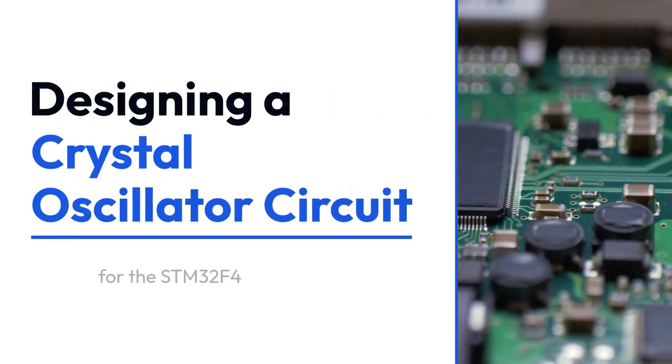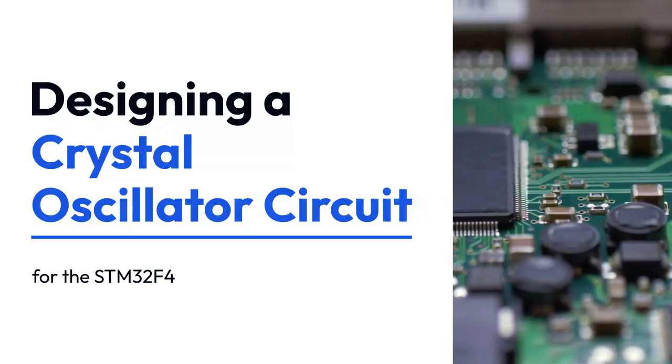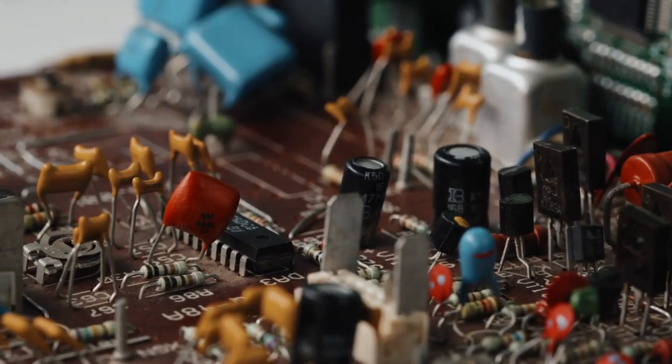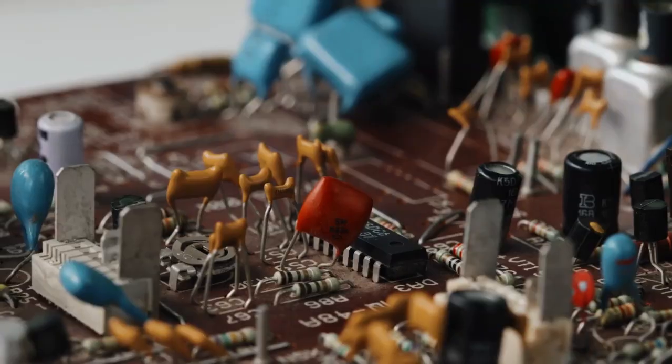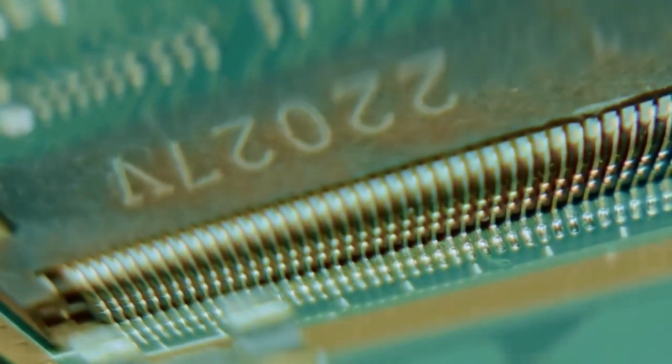We are diving into a crucial topic for any STM32F4 project, designing a crystal oscillator circuit. This circuit is the heart of your microcontroller's timing. It provides the precise clock signal that the STM32F4 needs to run accurately and reliably. Without a stable oscillator, your MCU could behave unpredictably. Let's break down the key steps.